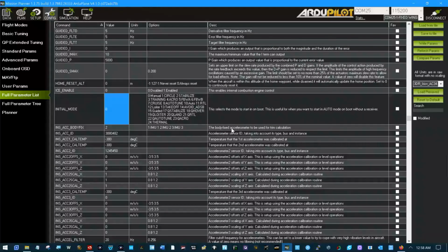It'll give you the tones to tell it, I got your high throttle, show me the low throttle now. You drop your low throttle down. It'll say, okay, I got your low throttle now. I'll give you some tones, tell you how many cells is in the battery and what the brake position is on the ESC, and sit there happily. You power down the platform, the flight controller. Your ESC is now calibrated. You won't have any problems.